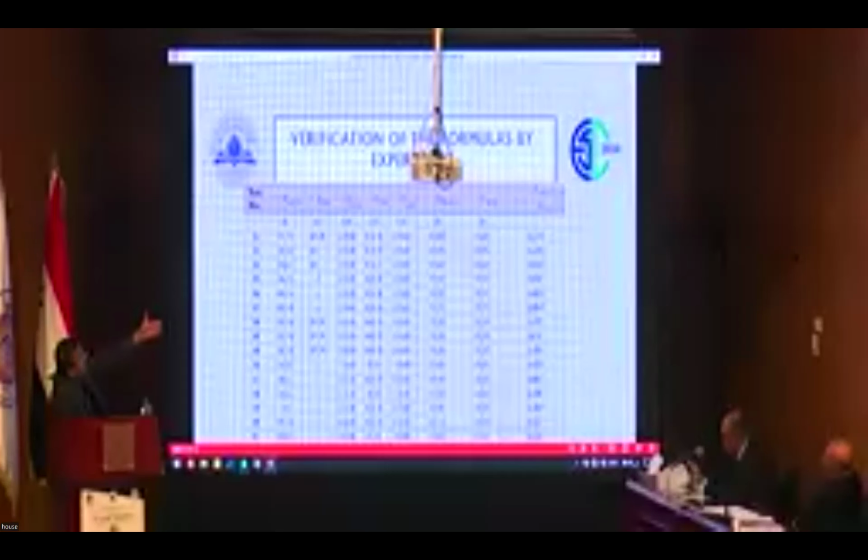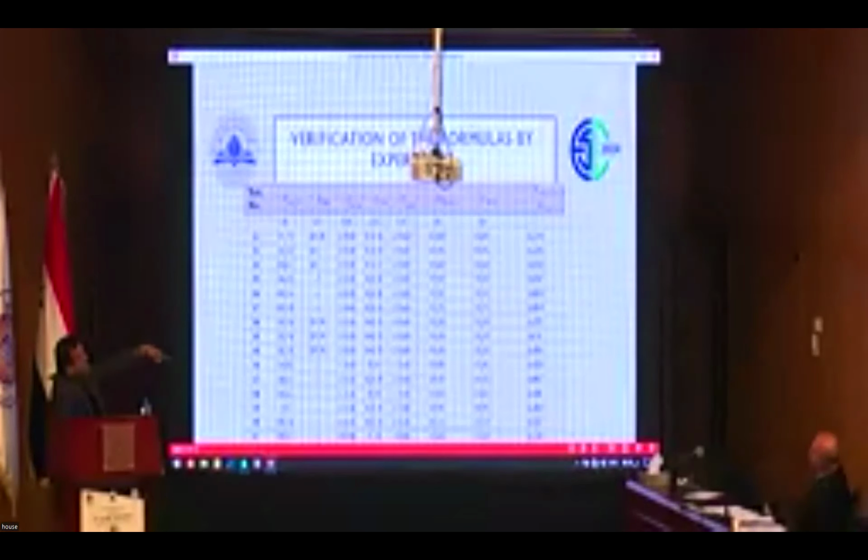It is the capacity recorded in the experiment divided by the capacity calculated by the formula. Normally, as you can see, the capacity observed in the laboratory is higher than what we calculate with the mathematical formula: 1.2, 1.2, and so on. We use these last numbers to calibrate the formula, or to better say, to make an uncertainty function, a probabilistic uncertainty function. Okay, please go to the next slide.